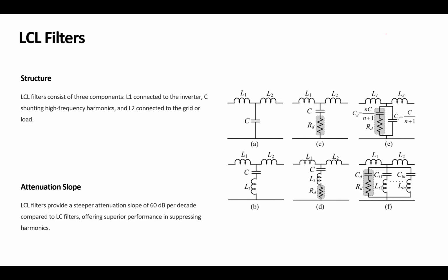The LC filter is more common because it's cheaper and it basically does what we want in power. Normally we don't have to go toward the LCL, but that's one type that a special kind of application might use. Same concept, just trying to use the matching impedance of the two L in order to increase the power transfer.